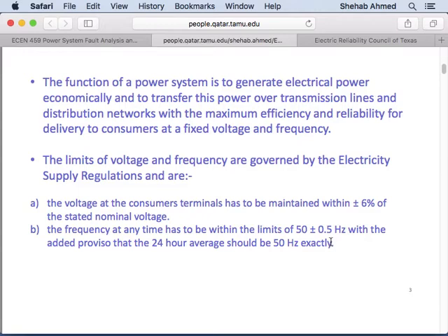So if you rotate the rotor one time, you will have voltage that is one full period, one full cycle. Rotate it fast, this one full cycle will happen in a shorter period of time. Rotate faster, shorter period of time, right? So it's directly proportional. The output voltage is directly proportional to the speed. So now if I keep loading, this electrical circuit keeps drawing more and more current, which requires more and more force on the windings, then what will happen? It's going to slow down. If it slows down, it deviates from the 50 hertz, right? So what do?